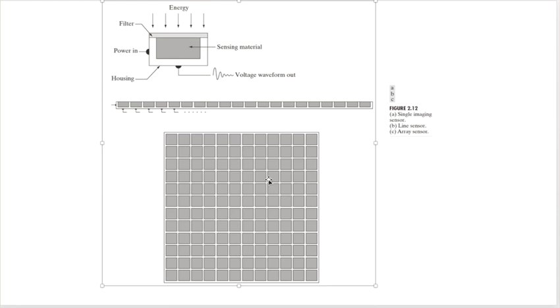It's called single event upset, SEUs. It happens all the time in space where you have a lot heavier radiation, much more powerful. It'll penetrate even through a lot of our filters. So we have to put better filters on the outside. We often have to do what's called a Faraday cage to protect it, right? Anybody know what a Faraday cage is? Yes, what's a Faraday cage?